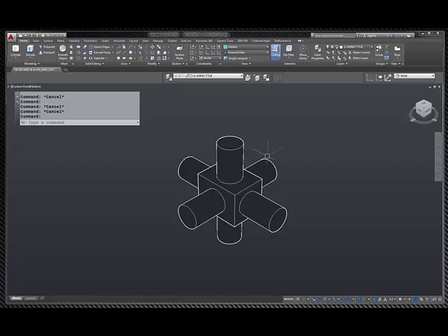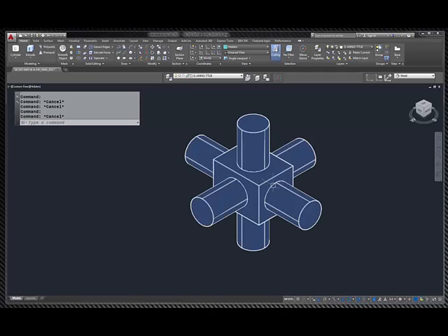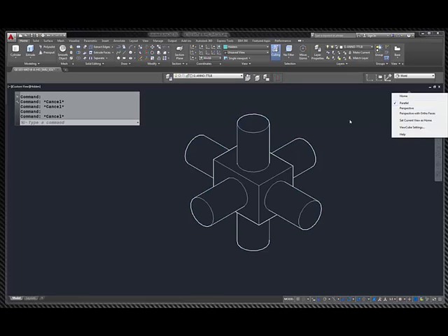One of the things about home, I want you to see up here, if you right click on home, we are in perspective right now, and everything looks a little flared. I'm a big fan of parallel. Doesn't matter if it works for you, that's great. Now if you want it to stay parallel and not go back and forth into perspective, right click again on the house and go to set view as home. And now it will stay as parallel drawing throughout the rest of your work, unless you want to go back and right click and change it to perspective.